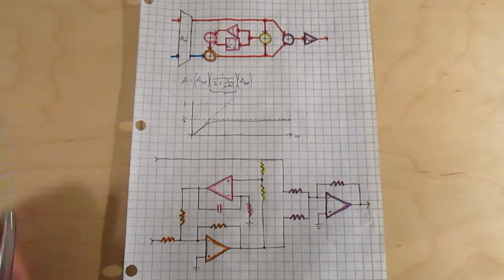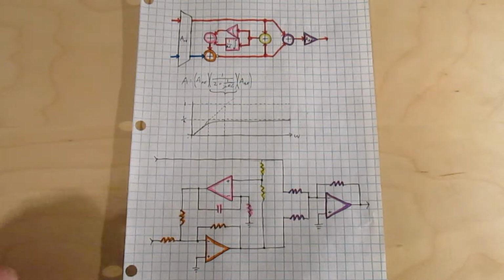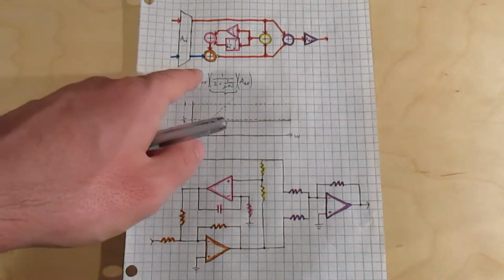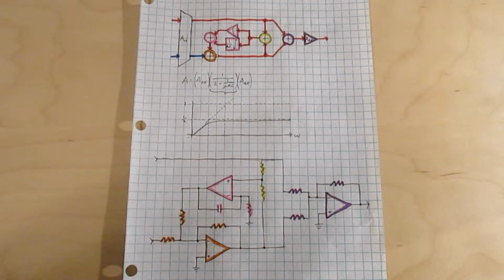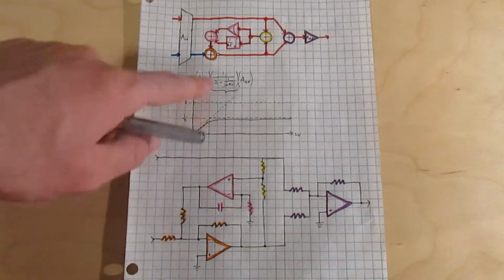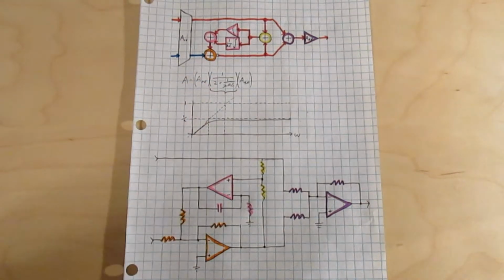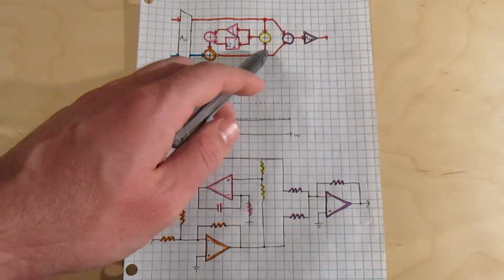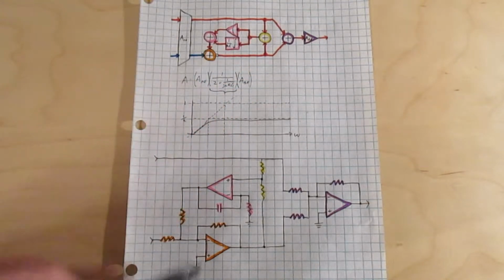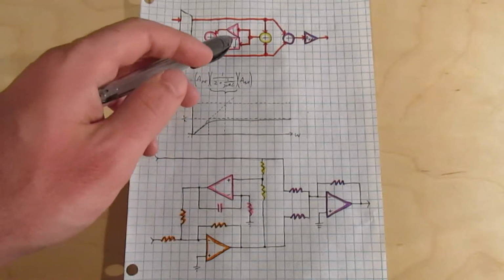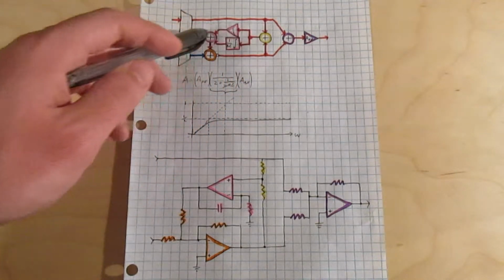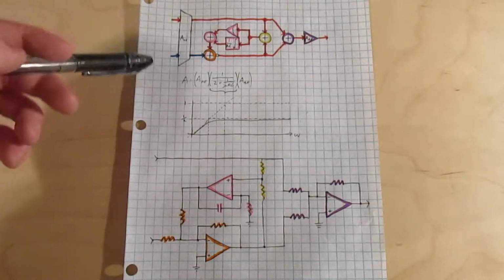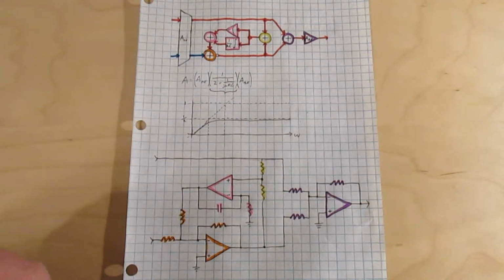And here's the equation for the gain of the entire circuit. It's got 3 parts to it: the front end, the back end, and in the middle here is the gain of the DC offset correction loop. And here I've plotted the frequency response of just the DC offset correction part of the circuit. So the job of the integrator is to look at the output of the circuit and find the DC offset, then feed it back to the input where it gets subtracted off. But Jason's circuit is not just an integrator, it also passes the original signal through, which means that at the input, the original signal gets subtracted from itself, and this lowers the gain.